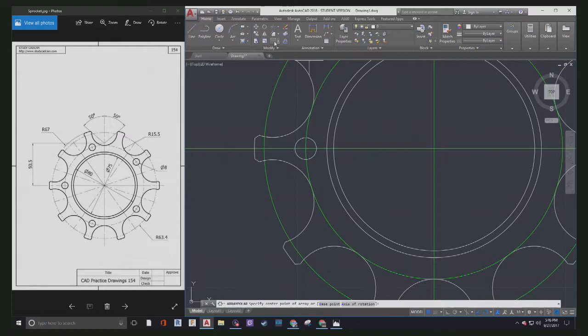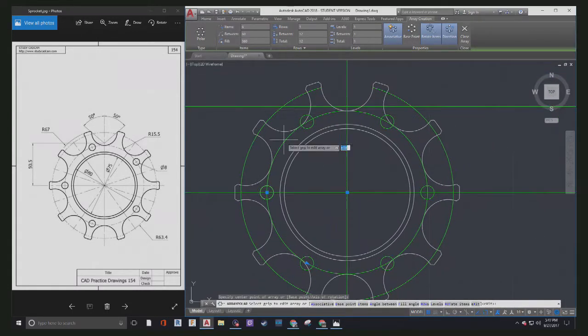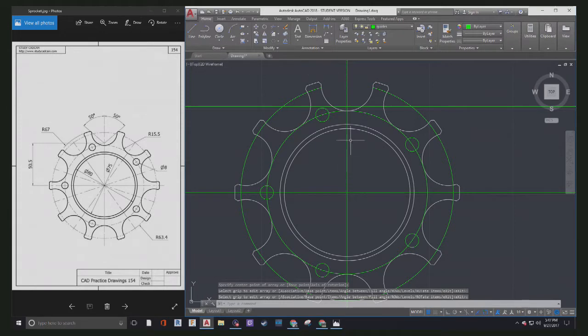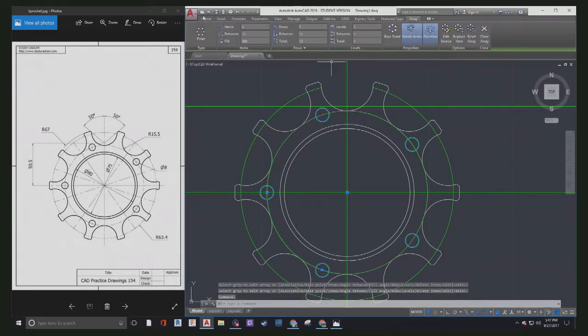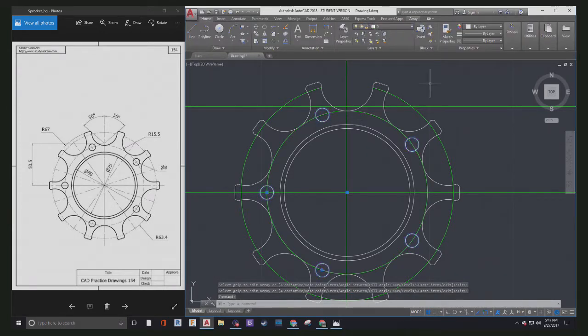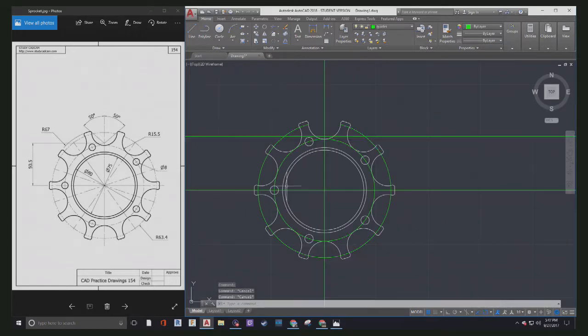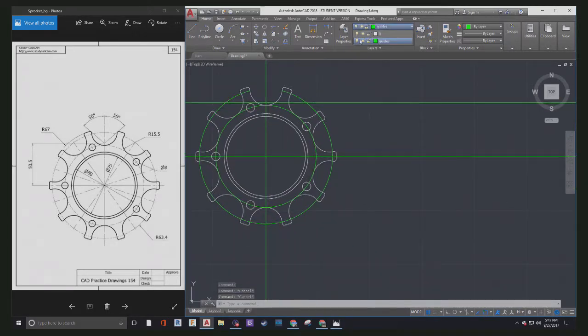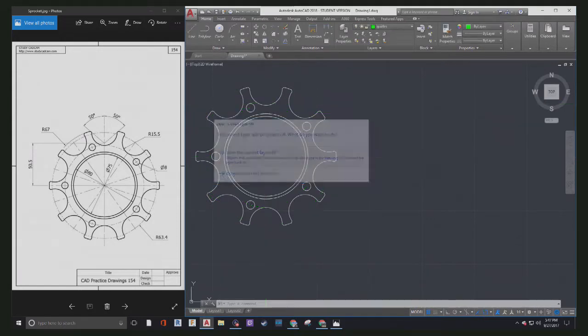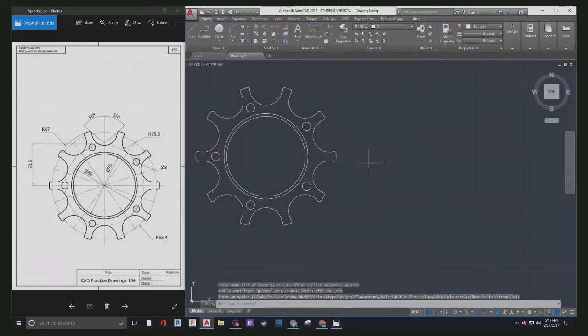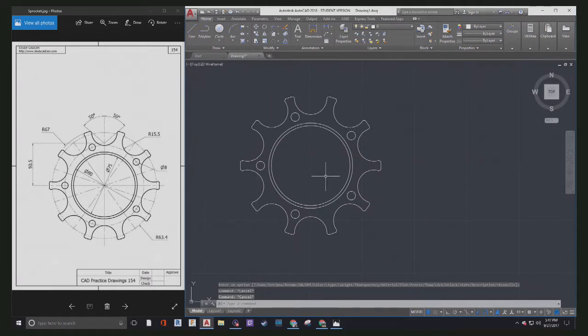And then we are going to do a polar array. The center point of that array is in the middle, and there are 5 items. When we update it, hopefully it looks correct. Yep, looks correct. Enter. Click on the array, go to home, and if it changed layers on you like mine, you can update that as so. Then we can turn off our guides, turn that off, make our white our current layer, and this looks correct.